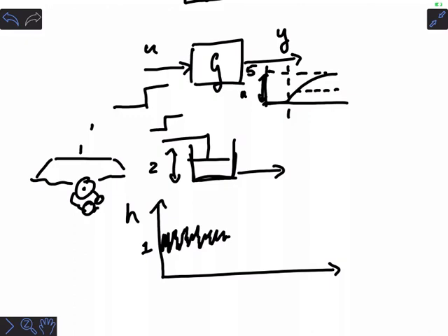And now you propose, okay, cool. I'm going to make a change that has the effect of moving to a new steady state of 1.5 meters, which is about there. Right? And so what that would look like with all this hairiness is something like this. And so you'd have a problem of distinguishing between the noise and the actual effect of the input that you've made.